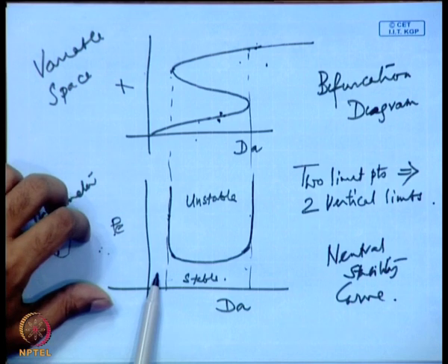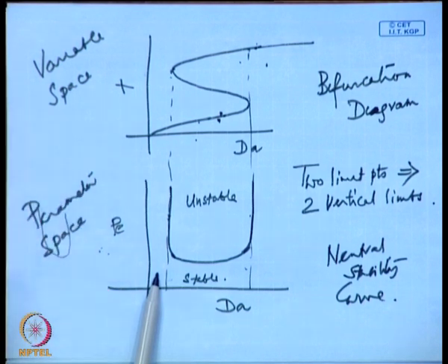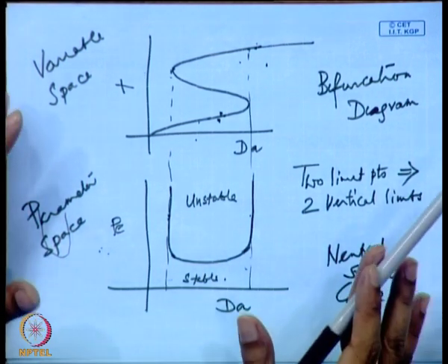If I choose something out here towards my left hand corner, complete left hand corner, then it will go to the extinguished state. So, I want two things. I want my system to be stable, and I want it to give maximum product. Which means that first it has to be on either the ignited or the extinguished branch, and second, it should be in the ignited branch.